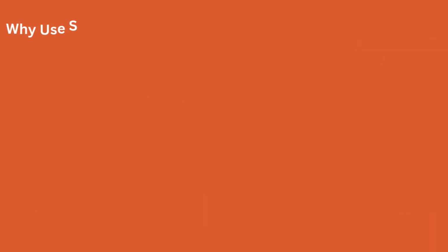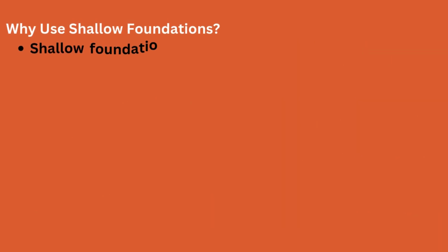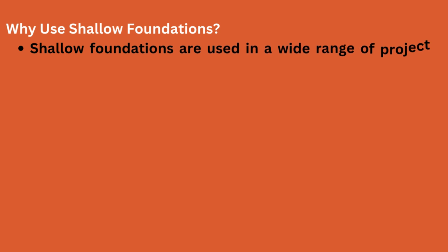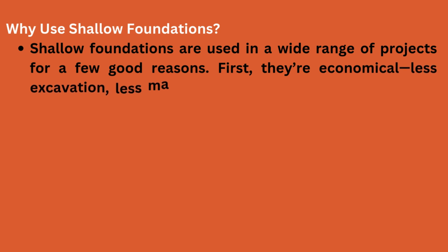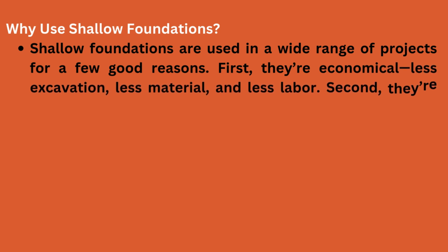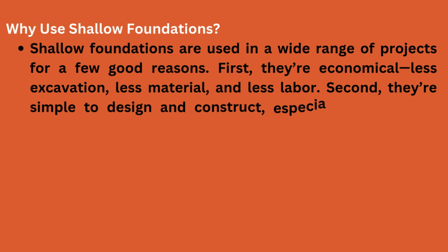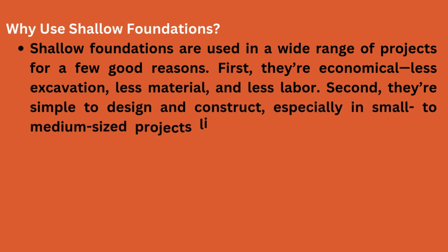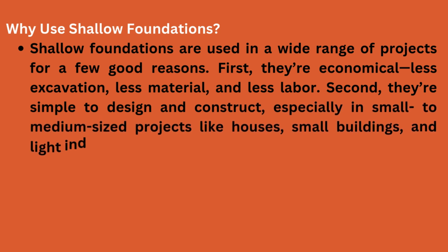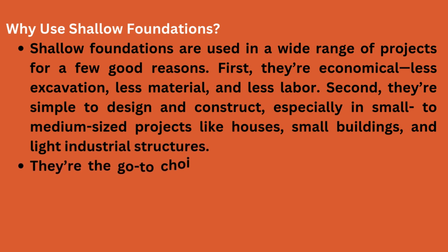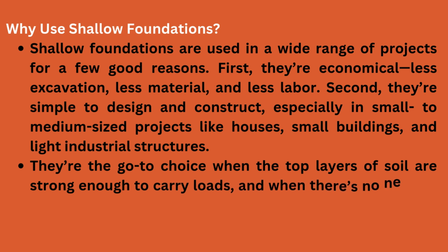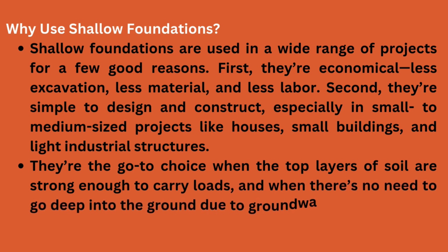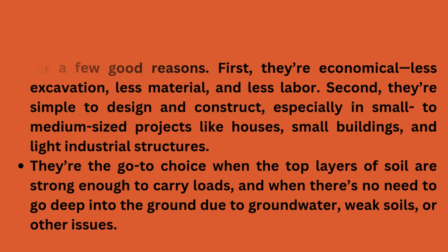Why use shallow foundations? Shallow foundations are used in a wide range of projects for a few good reasons. First, they're economical: less excavation, less material, and less labor. Second, they're simple to design and construct, especially in small to medium-sized projects like houses, small buildings, and light industrial structures. They're the go-to choice when the top layers of soil are strong enough to carry loads, and when there's no need to go deep into the ground due to groundwater, weak soils, or other issues.